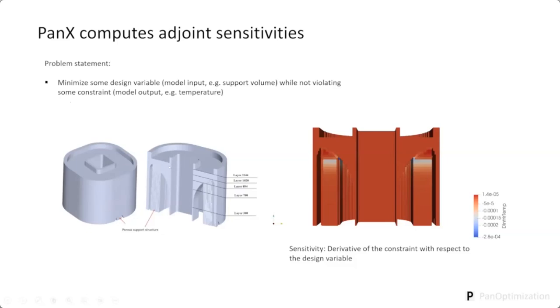And I'll introduce you to this geometry here if you're not familiar with it. So this is the canonical geometry. It's designed as a part of an America Makes project many years ago. Basically, as these thin walls start to transition into thicker walls, this section gets really, really hot. And it doesn't have a clear path of conductivity down to the build plate. So it's going to get quite hot in that area. It's a very clever design for testing the types of problems we're interested in.